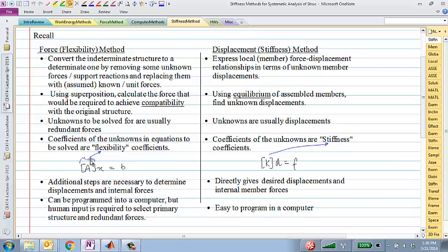Right. So we had to find the internal forces among all the members, and then to go to a specific node, find the displacement, x and y displacement, we applied a unit load, and then again recomputed the virtual displacements for each and every node. So it's a big task back there to find displacements of each and every node in the structure. Here we directly get those displacements.